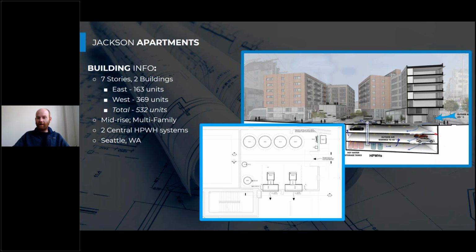But for the most part, if we locate these one story down, or maybe at the far end from the garage entrance ramp, we can allow that 25 or 23 degree cool air on our design day to warm up as it gets pulled through that ventilated garage before it makes it to our heat pump water heaters, so that by the time that air makes it to those heat pump water heaters, it's above their minimum temperature, and those heat pumps can provide heat to the water even when it's 23 degrees outside in Seattle.